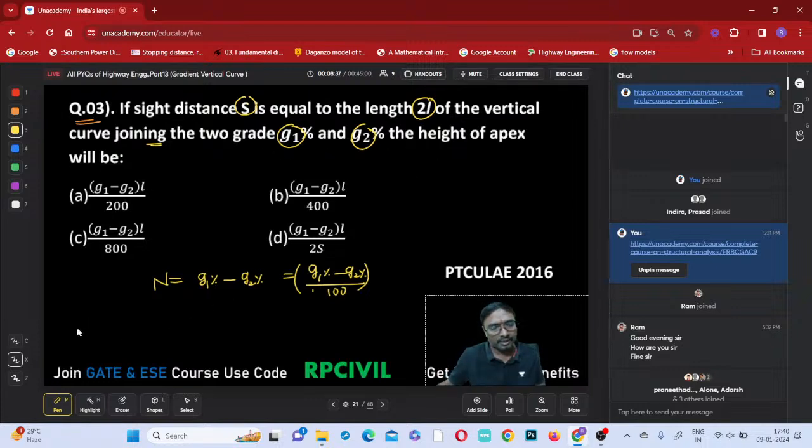And so here two gradients are meeting like this. This is your first gradient G1 meeting, this is your second gradient G2 meeting, like this you are having, right? Then you are asked to identify the apex distance, the height of this apex. This is your apex point, or this vertex. What is that? V you can say, if you just observe, that is your NL by 8, right?